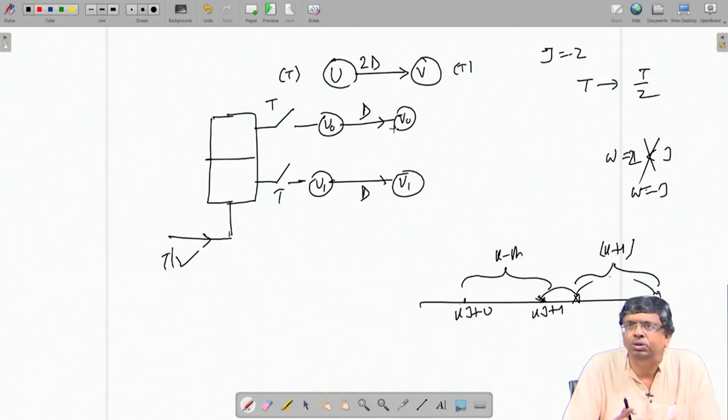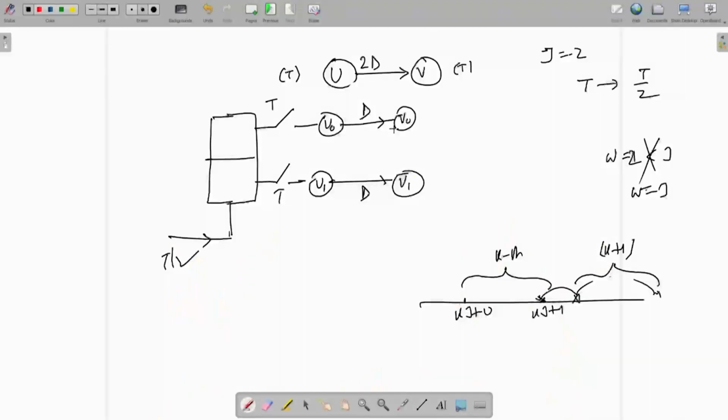So this has some theory actually that I will not cover, but those who are interested can read something from Parhi's book. Then it is posed more like this: after unfolding, if we want to have a particular critical path, that is, the unfolded system should not have a critical path greater than some value, say C, then how should I do the retiming of the original DFG, so that after retiming, when I unfold, the critical path of the unfolded system meets that requirement, that is, not exceeding that amount C. Okay, this is a theory. If you are interested, you can see it.